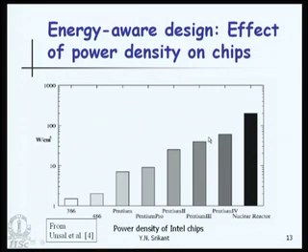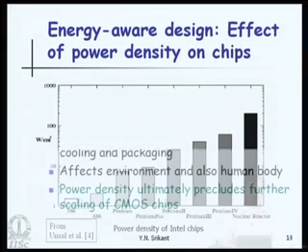So, if you look at the multi-core chip specification carefully, you will see that the frequency of each core is lower and the number of cores per processor is more than 1. So, what really has happened is you have reduced the power density; frequency being lower, the power consumption will also be lower. So, power density on the chips has reduced, but to make up for the loss of performance, the number of cores has been increased, so that if the software programmers are smart enough, they actually give you the same performance.